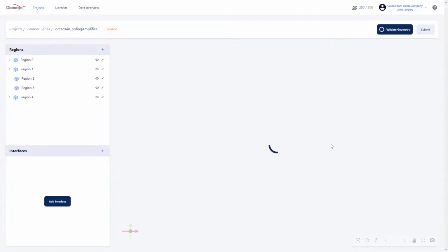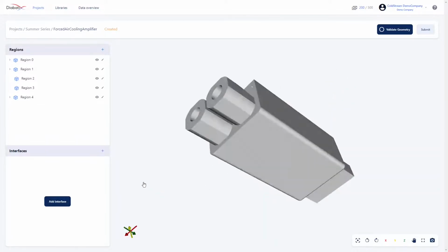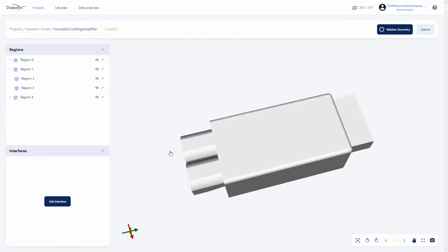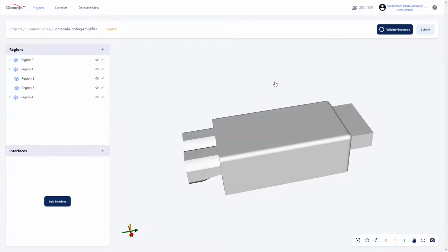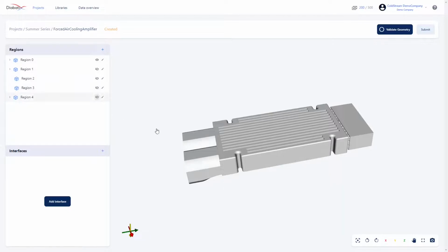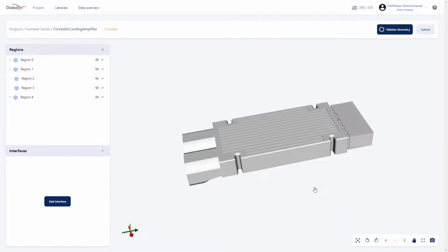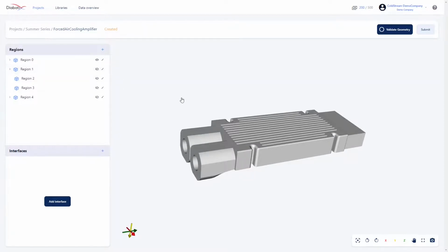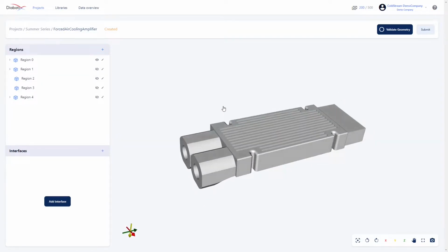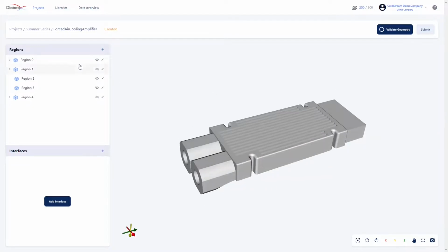For instance, the outlet filter and the manifold don't influence the simulation from a thermal perspective. So I decided to not make the simulation too heavy and to exclude them as real volumes or real solids in the simulation. But of course, what we did is we subtracted them from the fluid so that the fluid behavior is of course correct. So by that we go for the best of two worlds. So you can see now the fluid region and all the other regions.